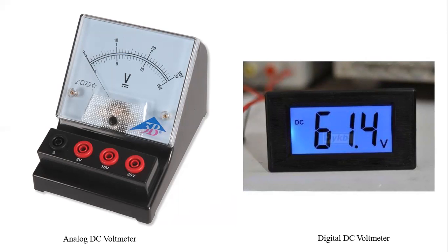We have to make one connection at the 0, and the other connection we can make at either 3 volt, 15 volt, or 30 volt, which are given for larger scales. Why have they been given? If our maximum measurement is 3 volt and we connect to the 30 volt knob, it will give a result, but the result will not be precise. So if we know that our maximum voltage will be 2 volt or near about 3 volts, we'll go for the 3 volt one for a more precise reading. According to that, the 15 volt and 30 volt knobs can be used.